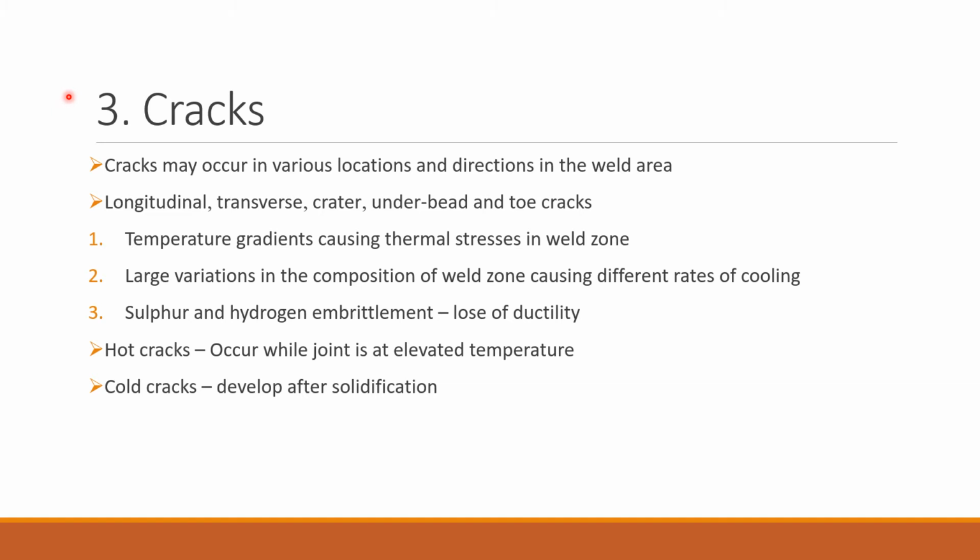Now the cracks are also differentiated on the basis of when they were formed. The hot cracks are called so as they occurred when the total weld zone was at elevated temperatures, and in case of cold cracks they develop after the solidification of the weld pool.